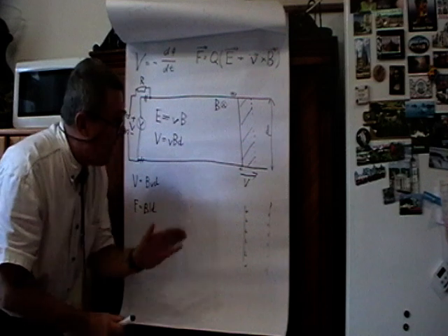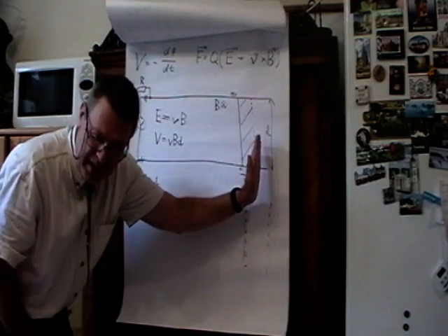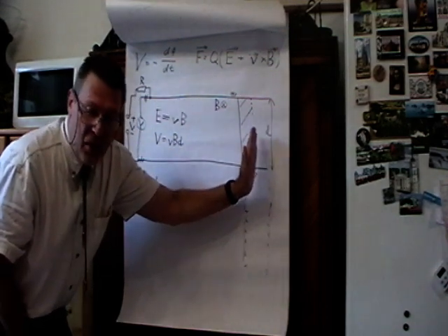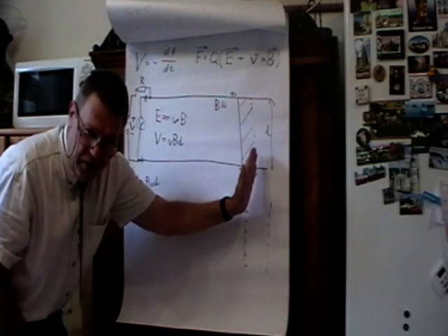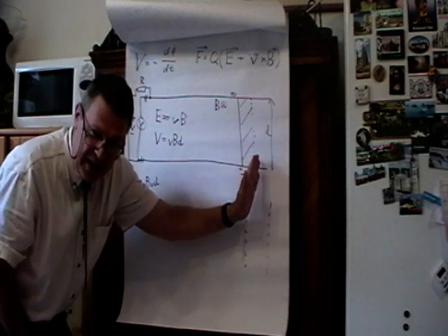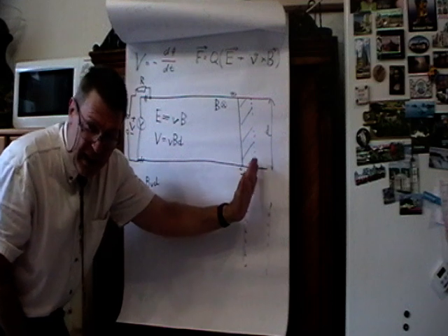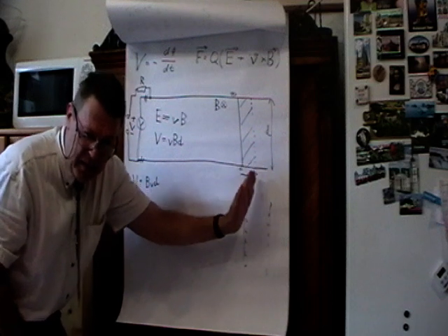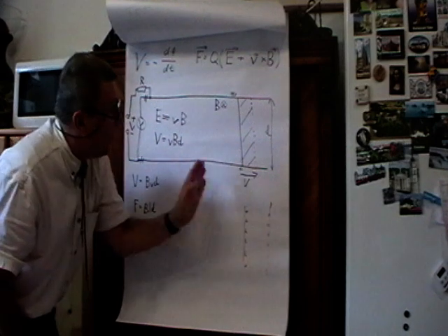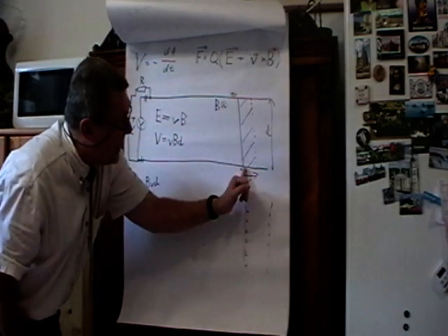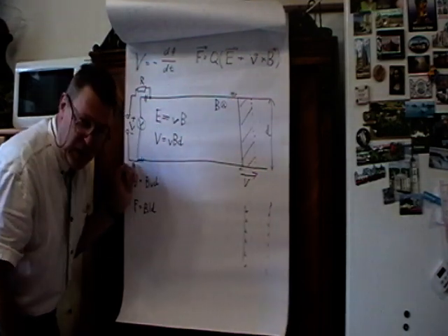as the voltage induced in the stick increases, the force driving current through the stick decreases, and there is a limiting speed at which the voltage induced into the stick would be the same as the voltage of the source.